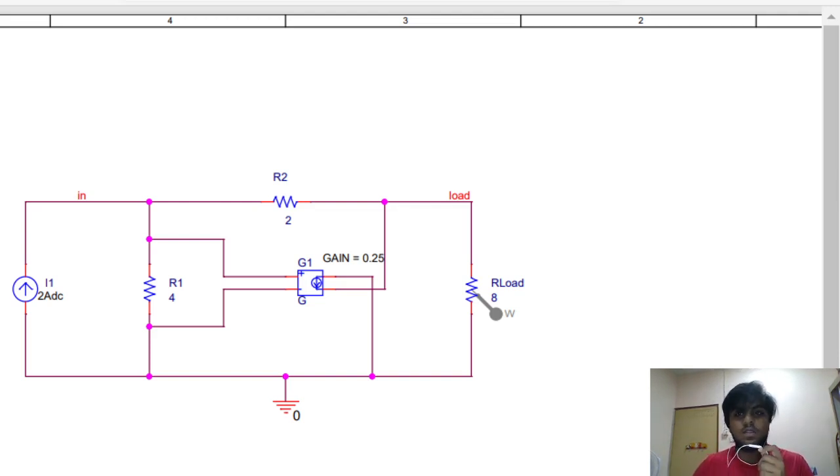So first of all, I'm going to present the Lab 3 Activity 1. Let me give you a small introduction about DC sweep analysis, which is the title of Lab 3 Activity 1. DC sweep analysis is used to calculate a circuit's bias point over a range of values. This procedure allows us to simulate a circuit many times, sweeping the DC values within a predetermined range. You can control the source values by choosing the start and stop values and the increment for the DC range. The bias point of the circuit is calculated for each value of the sweep.